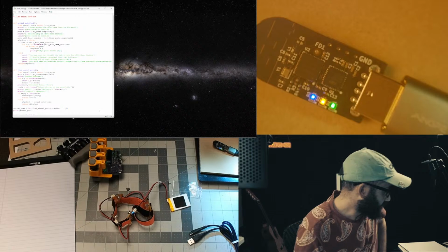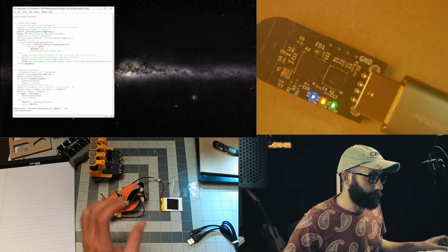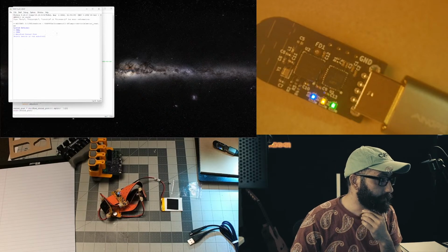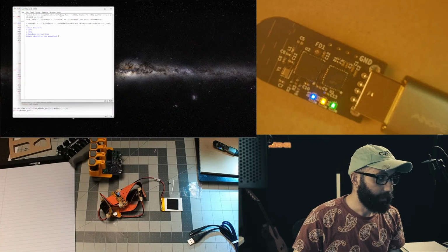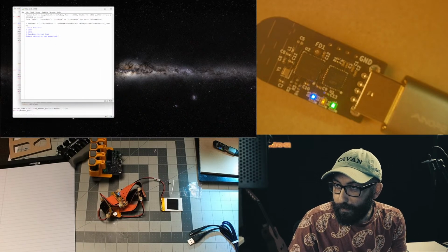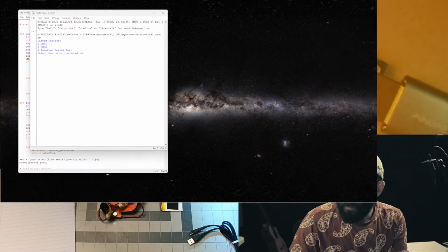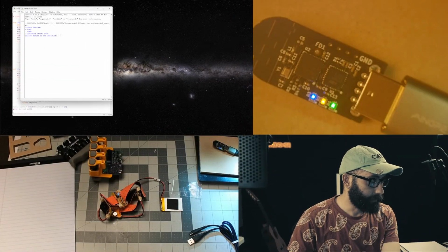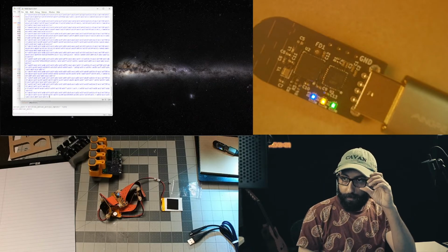Okay. So, now that we have this going, we should be receiving packets. So let's go ahead and go to serial read. We're going to run this, and it says it sees some COM ports listed here. You could probably barely see that. Yeah, it says some COM ports are listed there. Anyways, so I'm going to select COM port 6 by hitting 1, and it is receiving data.